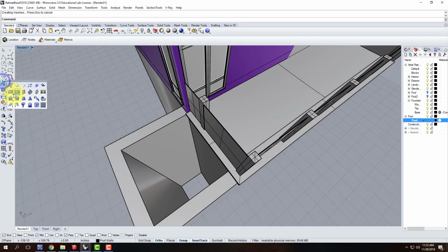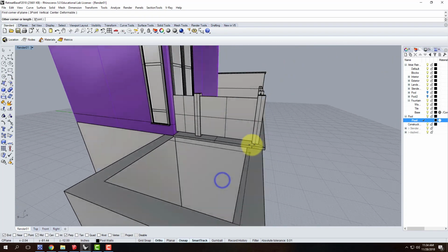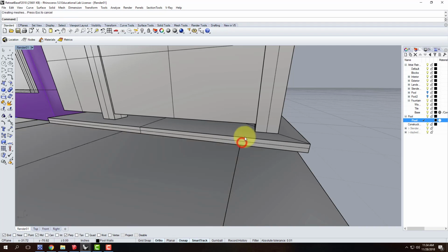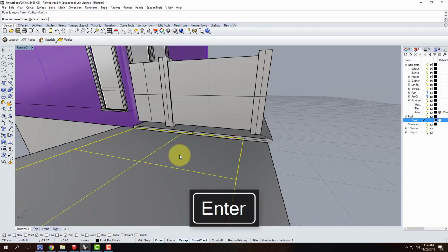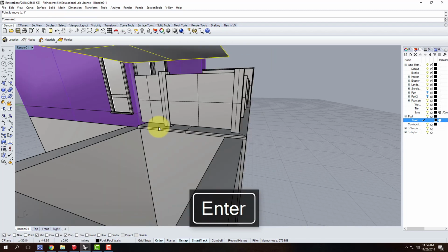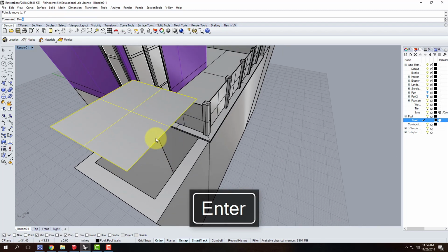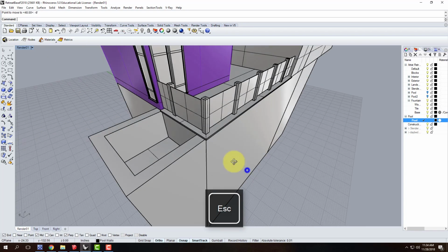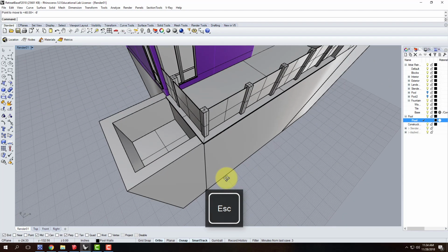Obviously, I need a floor that's not that deep. I don't need my hot tub to be that deep. So let me go ahead and create a floor. And then let me move this vertically, and we'll drop it down, I don't know, 4 feet or so. Oops, how about move vertical? Should have been -4 feet. There we go. And so we're creating the bottom of that pool.